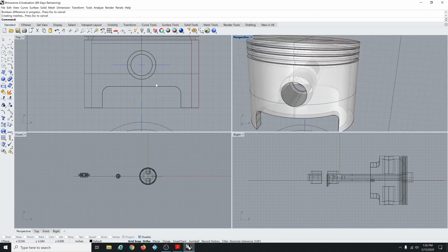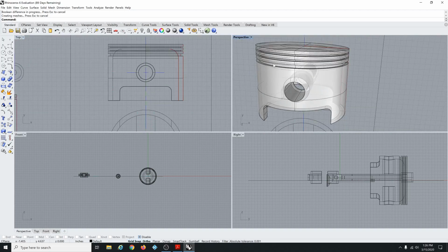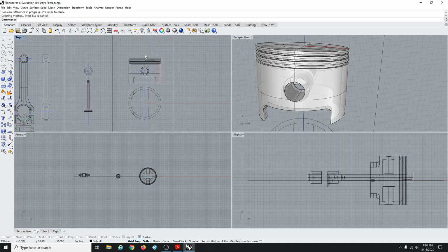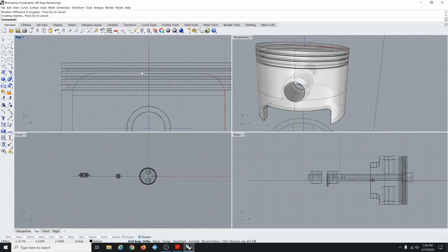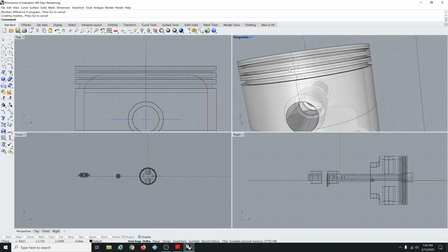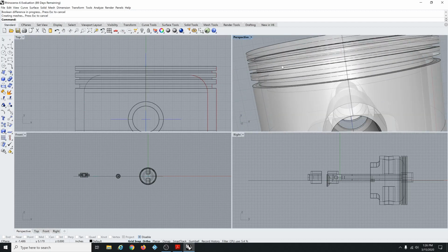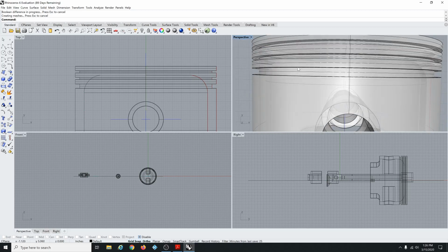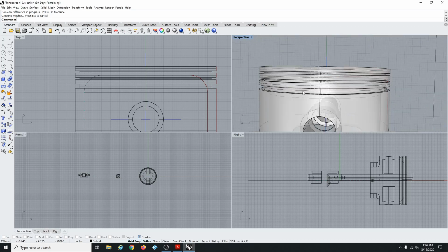All right, the last thing is there's these little oil holes we got to make. So those are, in a piston there's 3 rings. In this piston there's this first 2 rings are compression rings, and then the third ring is an oil ring, they call it. It just, oil passes through little holes and lubricates the sides of the cylinder. This thing is sliding up and down inside.